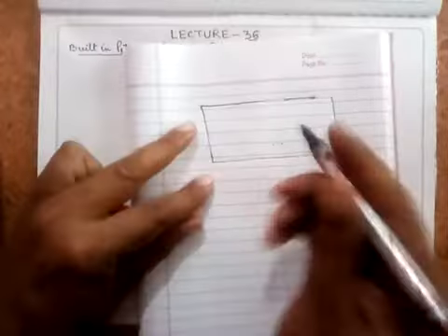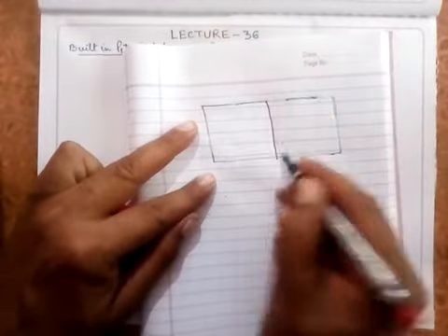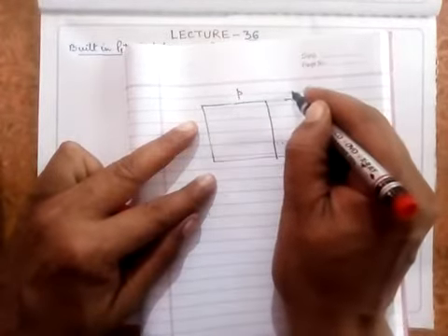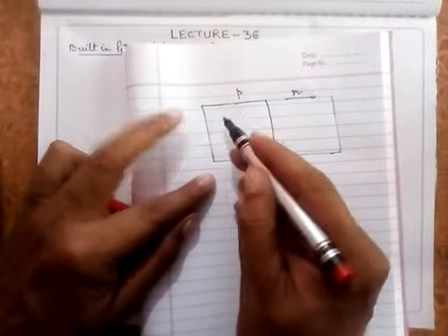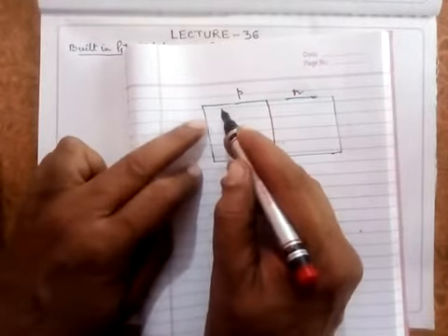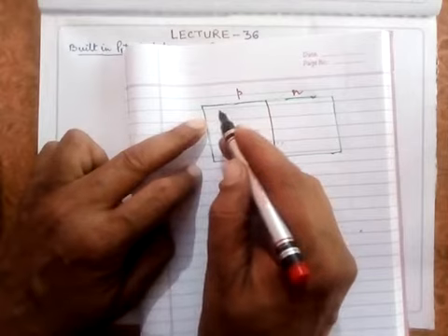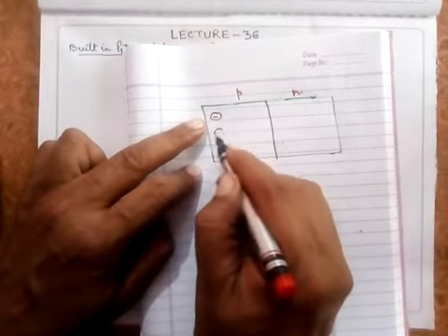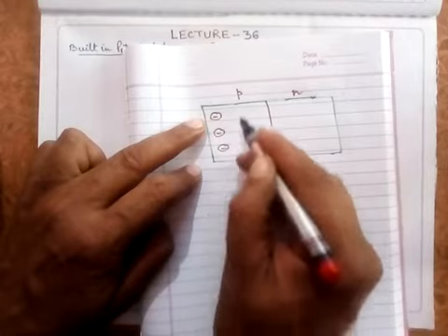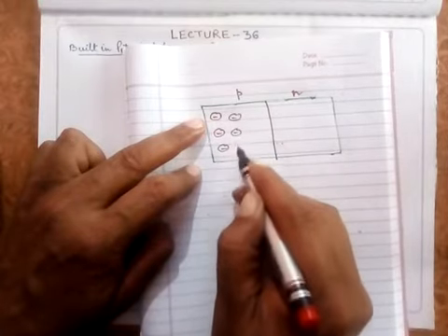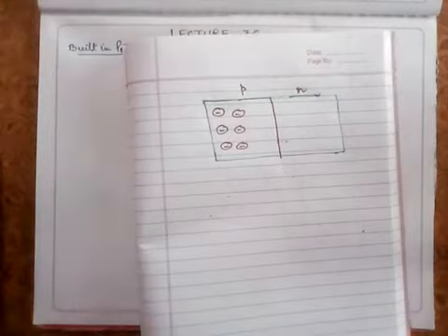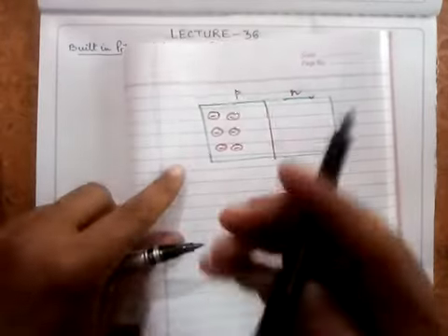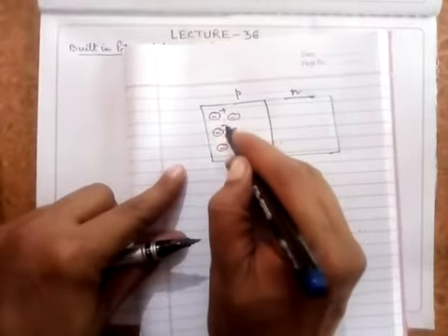And when I said that there's an open circuit, for example, there's a PN junction here. This is the P layer on this side and this is the N layer on this side. This P layer is formed by adding acceptor impurities, and every acceptor impurity accepts an electron and becomes a negative acceptor ion, with the release of a positive hole.